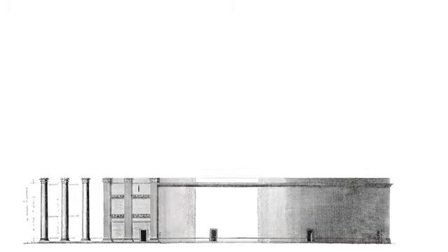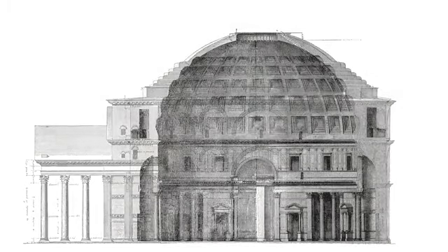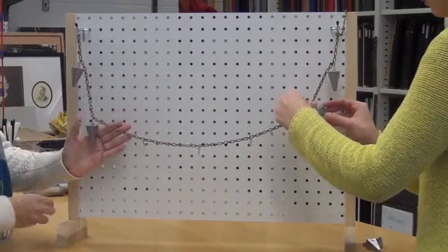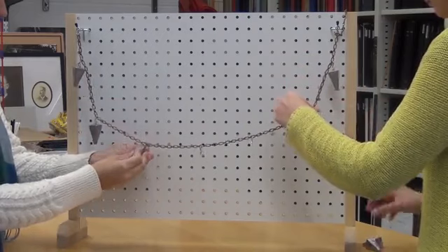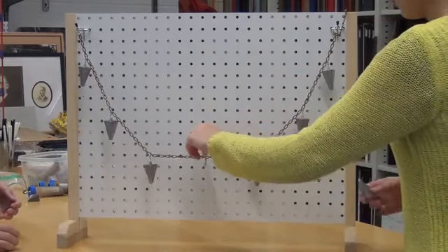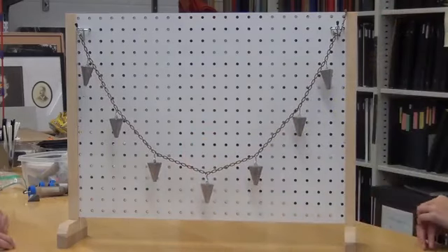The Romans probably saw the cracks develop and consequently loaded the sides of the dome near the supports with more stones and concrete to eliminate some of that tension. To understand the meaning of this, take a piece of string and load it uniformly with weights. That is, weights of equal amounts and equal distances. The form is essentially a parabola, as I noted earlier.